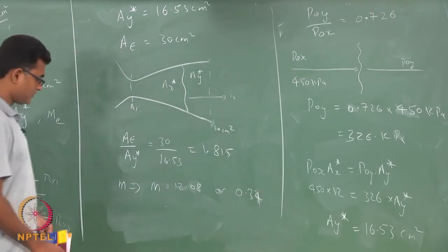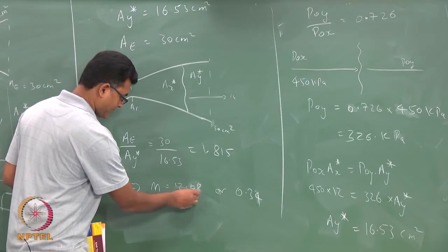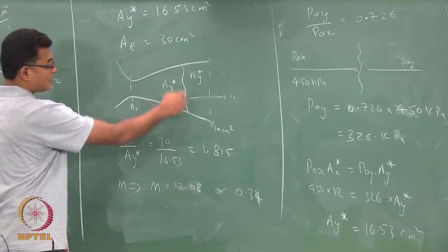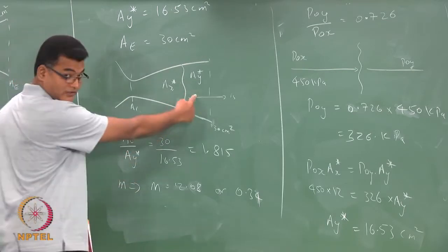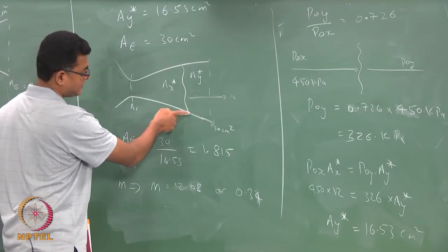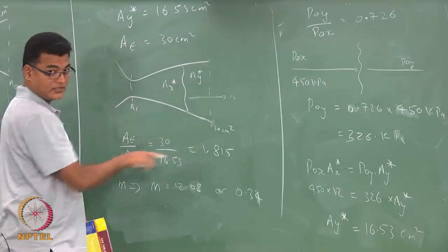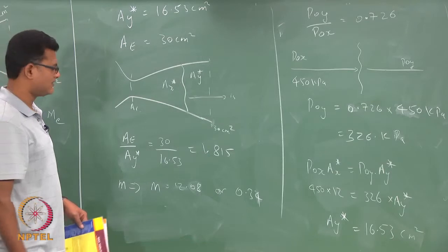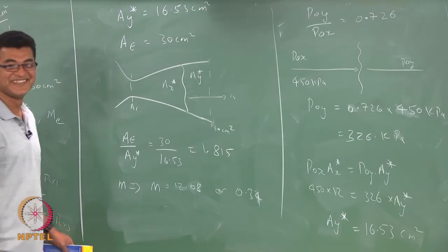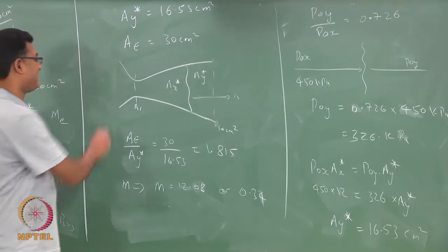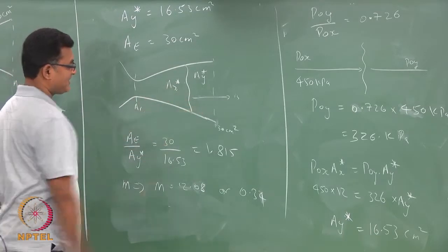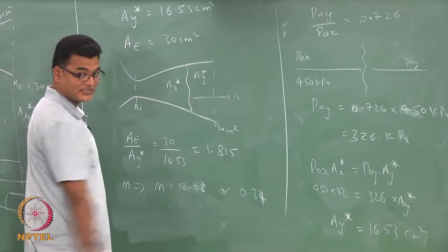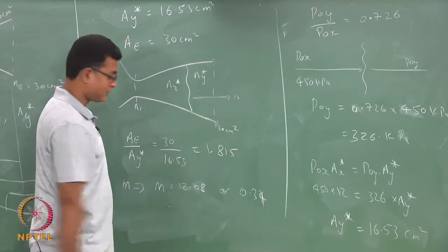Okay. Now the question is, which one will you pick? So now I have a strong normal shock, after which I have a subsonic flow. Now this subsonic flow still faces a diverging section. So I have a supersonic flow, I have a shock, after which I have a subsonic flow, and the subsonic flow faces a diverging section, so it continues to be a subsonic flow.